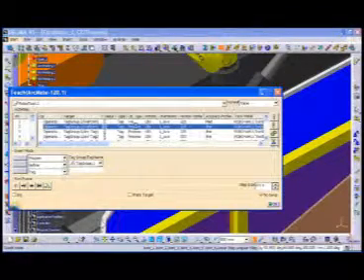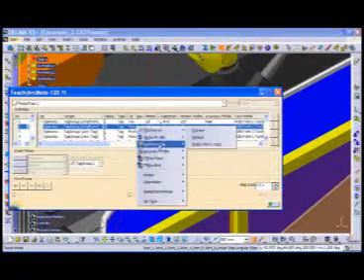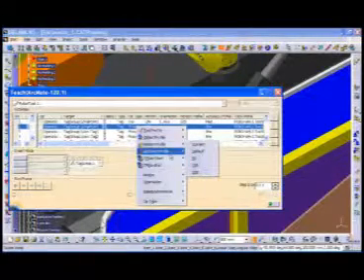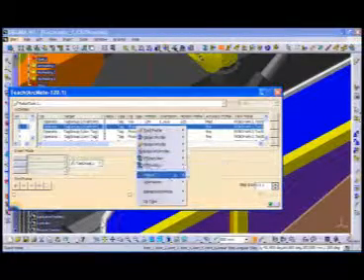We can adjust the speed and accuracy of the robot program. We can also change things like interpolation style, which affects the motion. The wrist configuration, tool point, and U-frame can also be changed easily in the program.